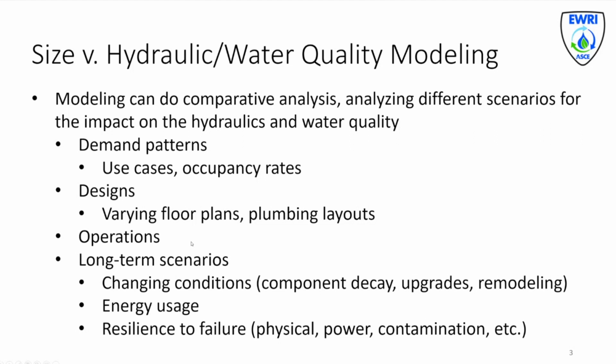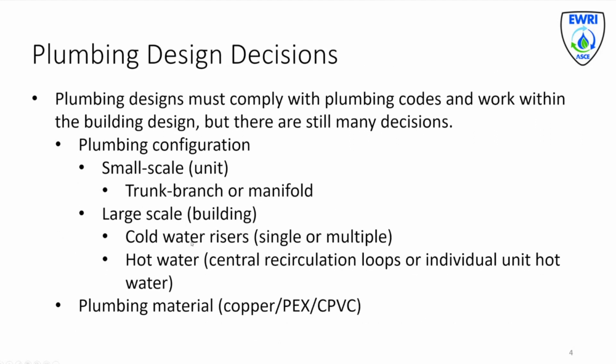And so in what we've discussed today, these fit into three different areas that were discussed. The first is the plumbing design, what the plumbing engineer is going to lay out and will hopefully be constructed. They have to comply with the plumbing codes, but there's still a lot of decisions that have to be made. A couple of quick examples are the configuration. On a small scale, is it trunk and branch or a manifold system? At a large scale, where do the risers go? Is there a single riser or multiple risers?